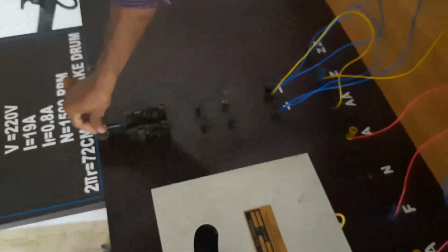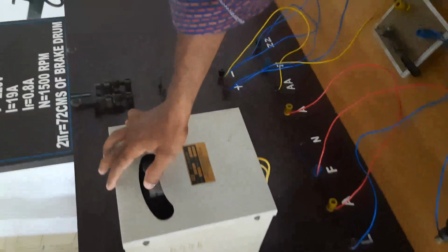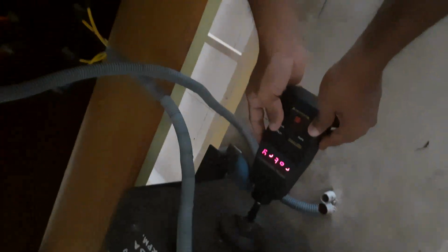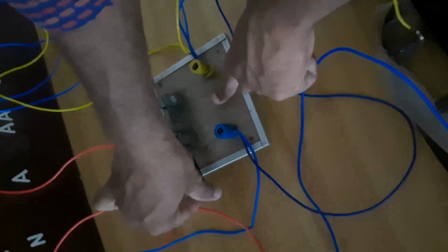So let's start the experiment. First, we have to close the DPST switch. Then with the help of starter, we need to start the motor. Once the motor is started, we have to check for the speed. So it is already 1500. Then there is no need to vary the field resistor. Okay. Then we are going to open the SPST switch and we are going to note down the readings of field current, load current